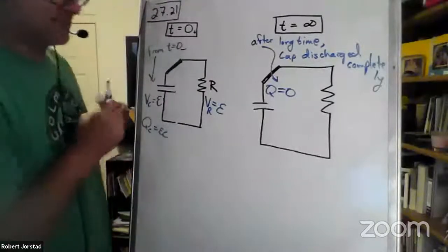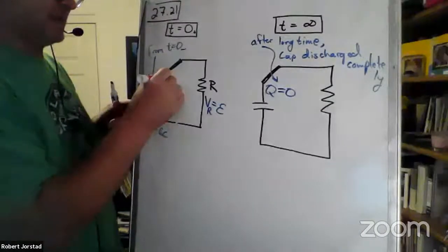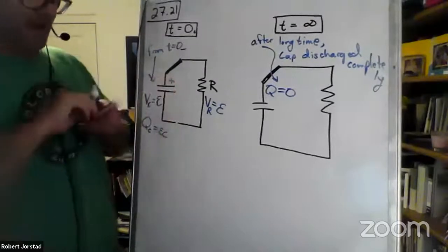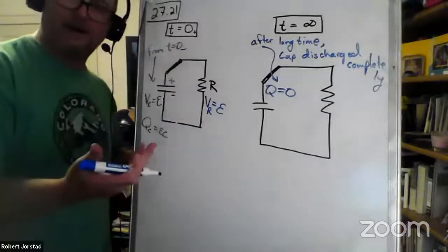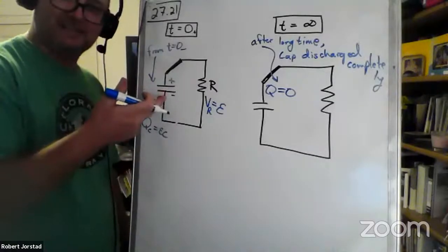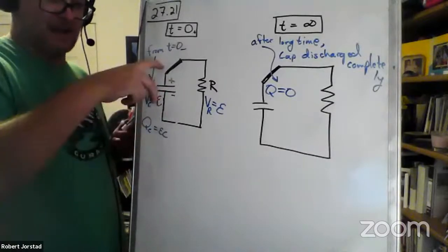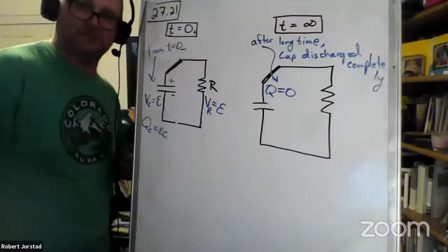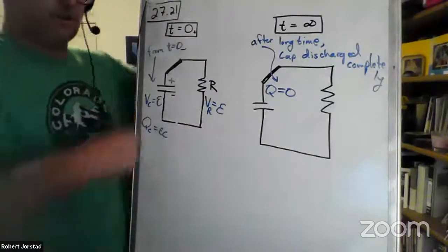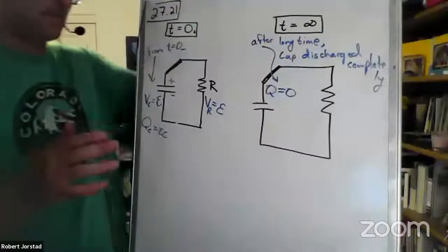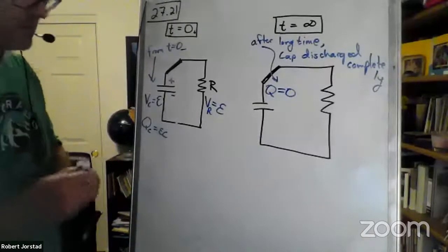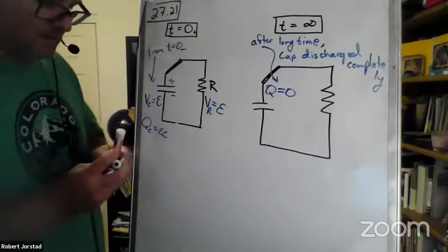Think about it. If you gain E volts on this side, remember this capacitor is going to have a positive plate here and a negative plate right here. And it is the source of energy that's driving the current now. It's like the battery. So if you gain E on this side, you have to lose E on that side through the resistor if you go around the loop. Does that make sense? Yeah, I gotcha. Sneaky, right? Not exactly obvious at first. Go ahead, Eston. Did you have a question or no? Oh, no, I was just saying, yeah, I get it now. Yeah, it tricked me. Okay.